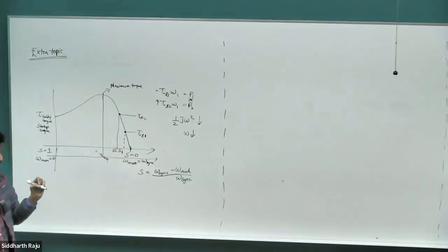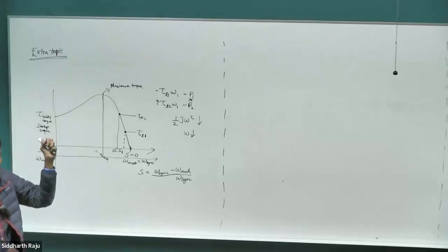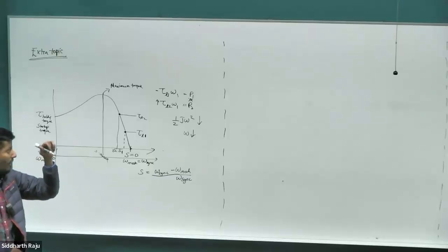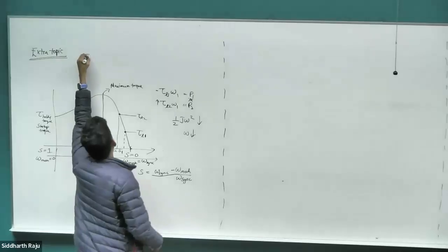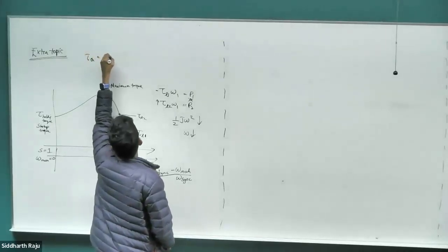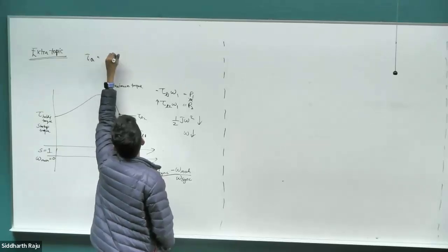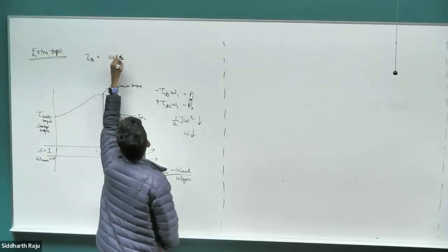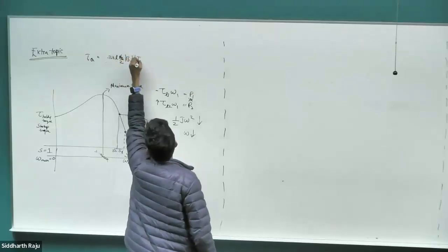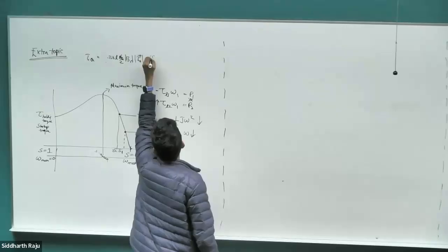This is exactly the same as what happened in a permanent magnet synchronous motor. Up to delta equal to 90 degrees, it was operating at a stable point. For a given current, our torque equation was 3 by 2 times pi R L n_s divided by 2, times B_r magnitude, times I_s space vector, times sine of delta.